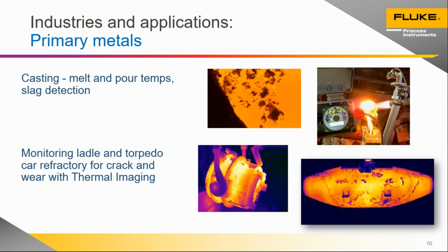What that company had been doing up to that point is using just thermocouples dipped into that pool to get the measurement. Of course, one of the troubles with that is that they nearly had to replace the thermocouple each time it was used, so it adds up over time to be quite an expensive way to do it. And we got very good matching of readings between the infrared reading and the thermocouple reading in this case. All you really have to do is make sure you have a good moving fluid with enough mixture so that the surface temperature matches well with what's under it, and you can do that measurement through infrared quite well.